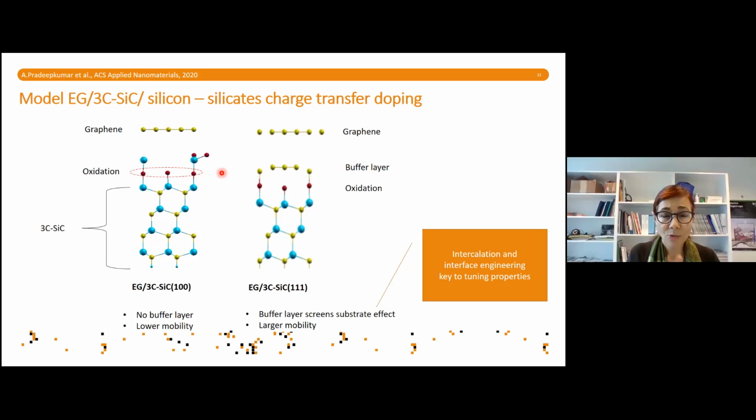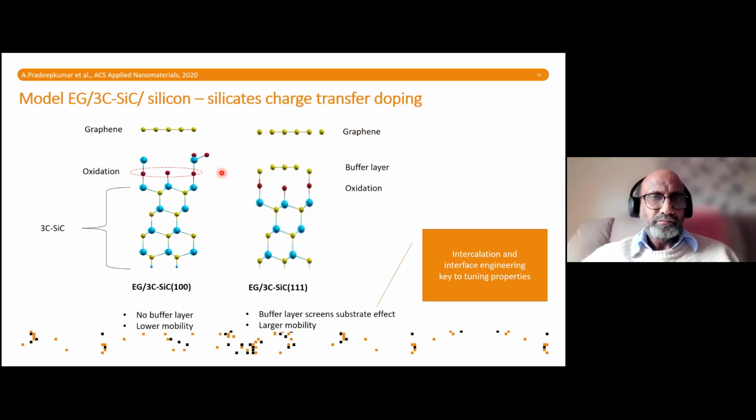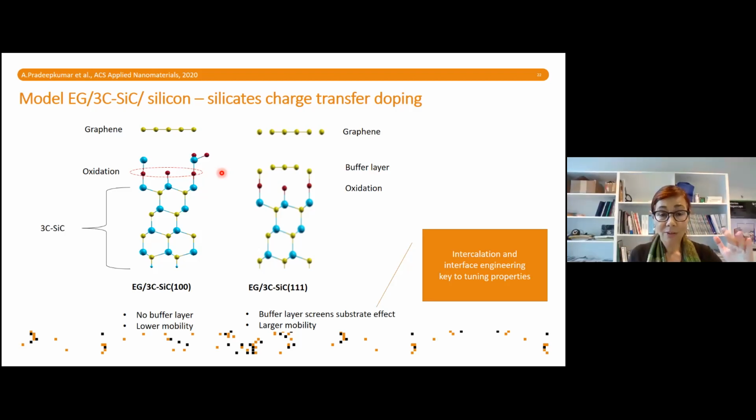Your question is about what is limiting the grain size? Well, on the epitaxial graphene on the actual silicon carbide wafers, they have already reached micron and higher. Indeed, in some cases, you can see that they can also reach ballistic conduction. If they have a certain step on the silicon carbide, they can create a nanoribbon where they can even reach ballistic conduction. But that's a different system.